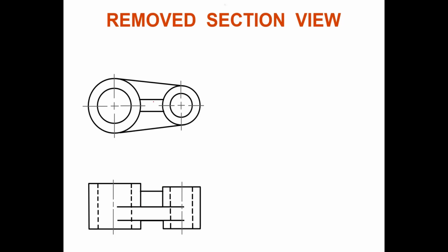We can't help thinking, how does it really look like? You don't have any isometric drawing here because you are doing orthographic drawing. In the middle here, what does it look like? What is the cross section? Is it T shape, or I shape, or just a rectangular shape? This is significant to be shown by sectioning.